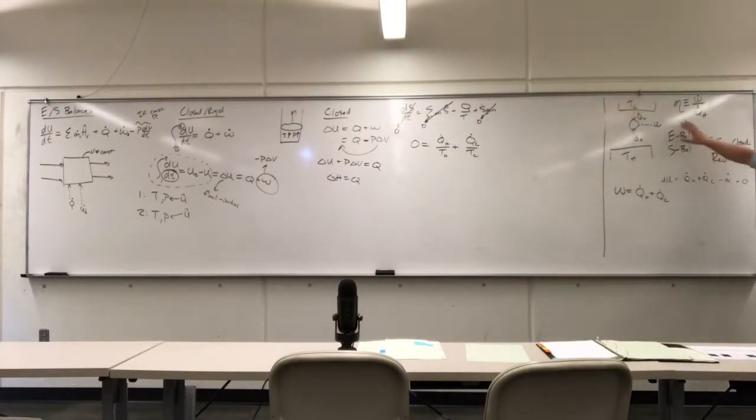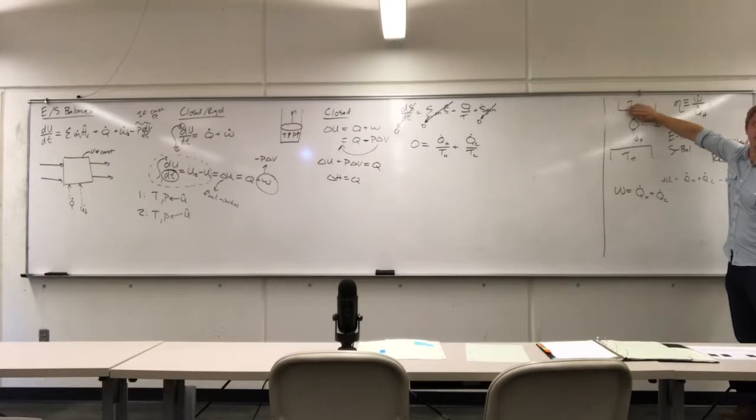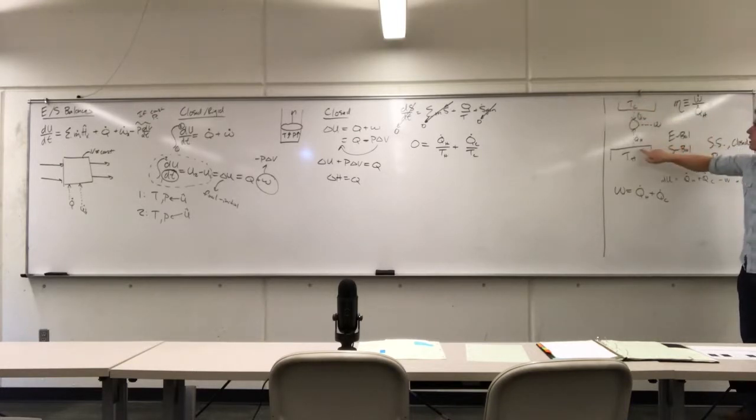Right, so we have a furnace that is providing energy to some magical process that is then somehow producing work. Now, if we didn't have this cold reservoir, this would be the Kelvin-Planck violation of the second law, right? Due to the directionality of entropy, you can never take heat and turn it into work. Work can only get converted into heat.